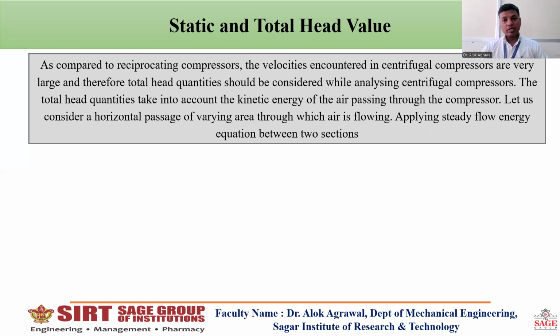But in the case of a centrifugal compressor, the RPM of the rotating element is very high, and so the velocity of air or gas encountered with it is also very high. So it is not possible to neglect that velocity, as a lot of energy is associated with it. In that case, we need to talk about the total head quantity.